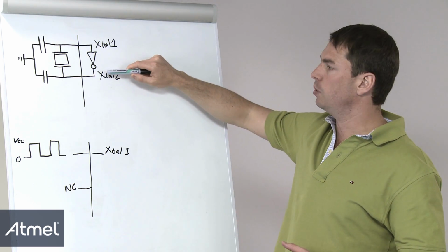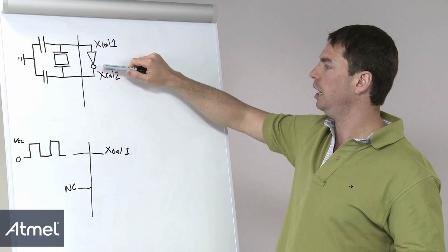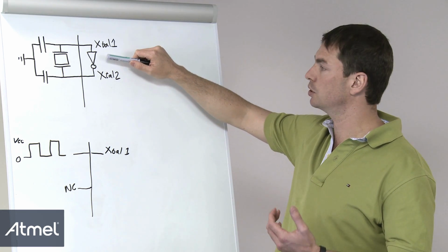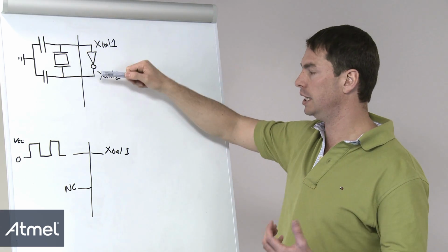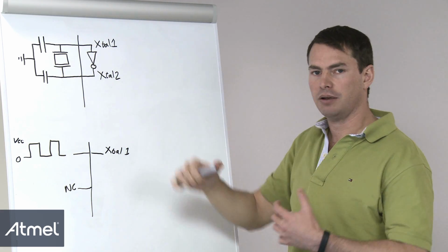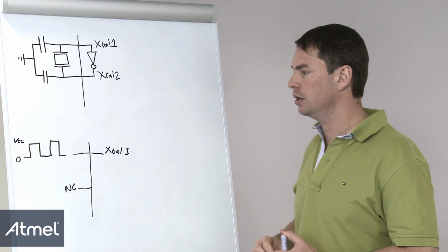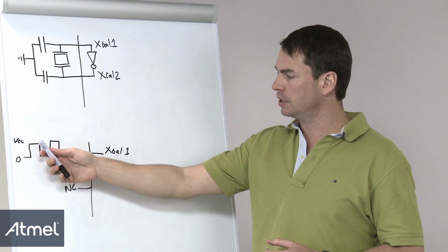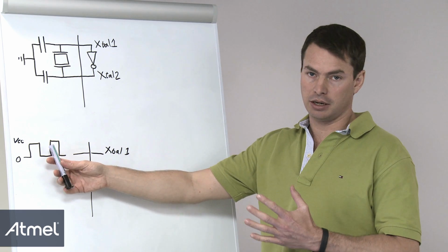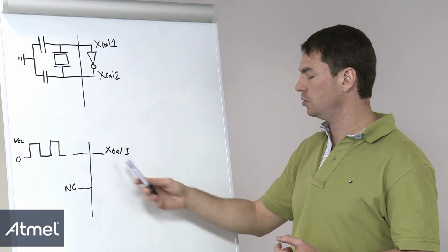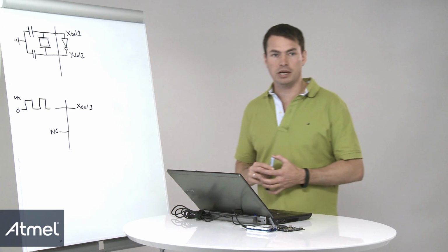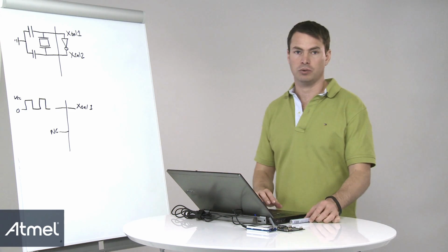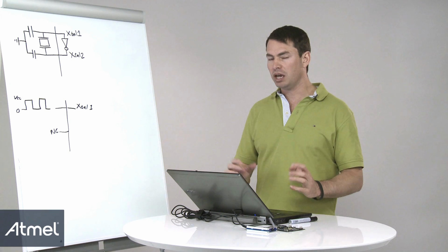Internally in the AVR, when we select an external crystal, an inverting amplifier is used, and this is important to actually get the external crystal oscillating. If we, for instance, chose an external clock, we supply a perfectly square 0 to VCC clock source signal into the crystal 1 pin.